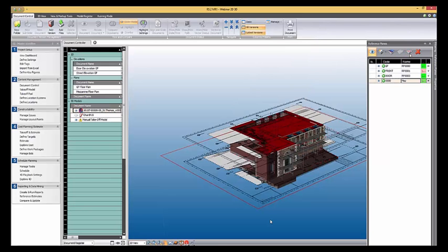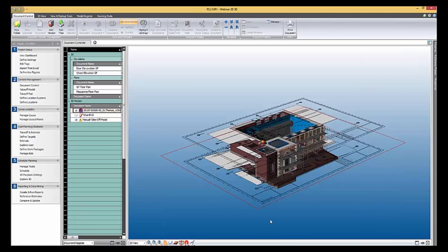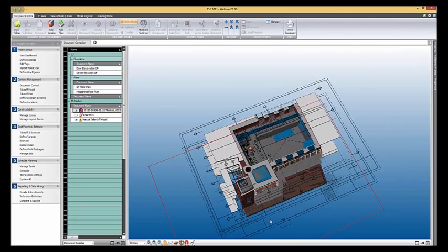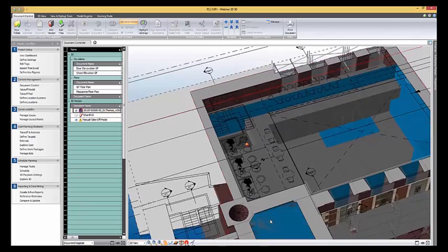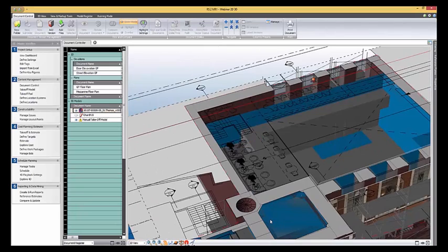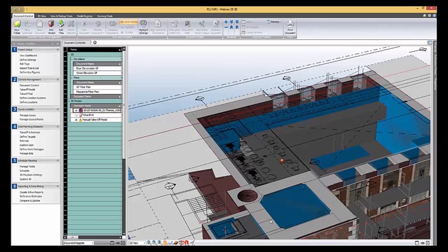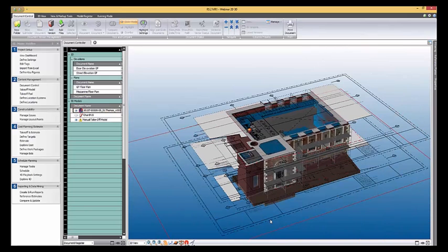So I can use any one of those drawings to cut that model in a section, and as long as I turn off capping I can see a bit better. If I view here, you can see I'm taking a simplified model and then adding detail from a drawing, so I can really combine the disciplines to get a full understanding of what's going on with this project. I can also do some visual analysis to just check that the drawings do match up to the model.